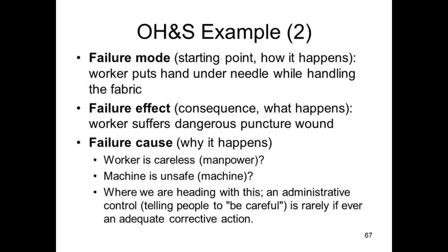The failure effect: remember, the failure mode is the focus element or starting point. That's what happens, what goes wrong, how it happens. The consequence: worker suffers a dangerous puncture wound, severity of 10. Failure cause: worker is careless. That's not a valid failure cause in terms of solving the problem. Now, when we see machine is unsafe, that might be a better place to look.